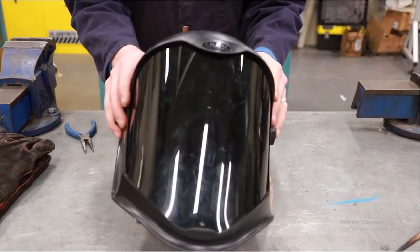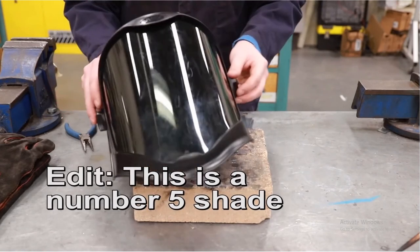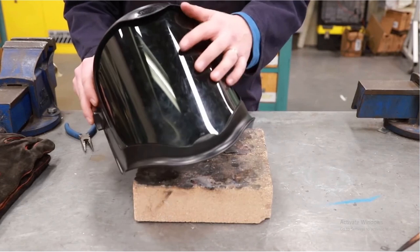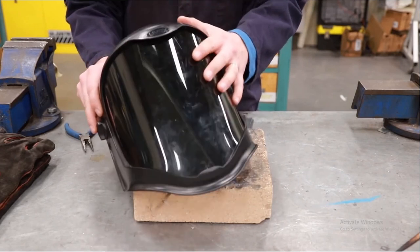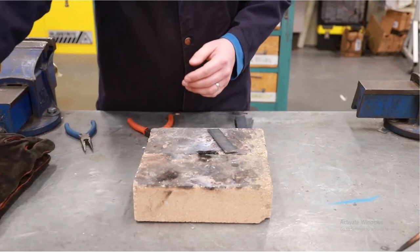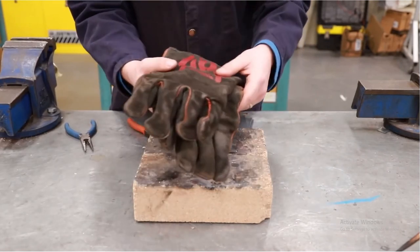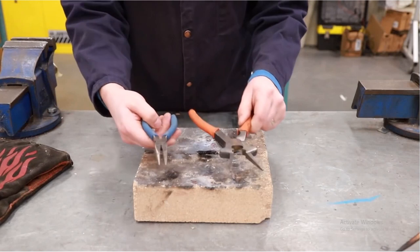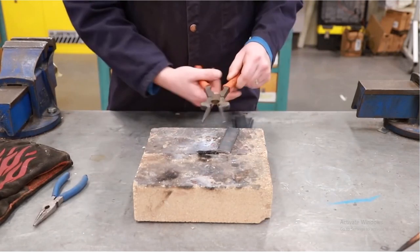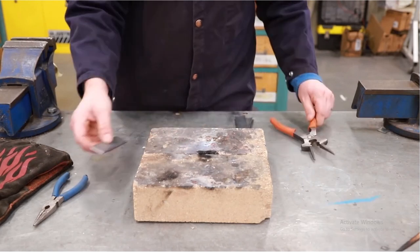Next, you need to have some sort of eye protection. We're going to be using a number 9 screen here. This protects your eyes and your face from the heat, mostly your eyes, so that your eyes don't hurt while welding. Welding with just bare eyes is going to hurt for a while. You need to have a set of gloves ready. We're using leather gloves here to protect from burns. And I've got pliers here to pick up hot material after we've been welding. If you pick up hot material with bare hands, you're going to get all blistery.